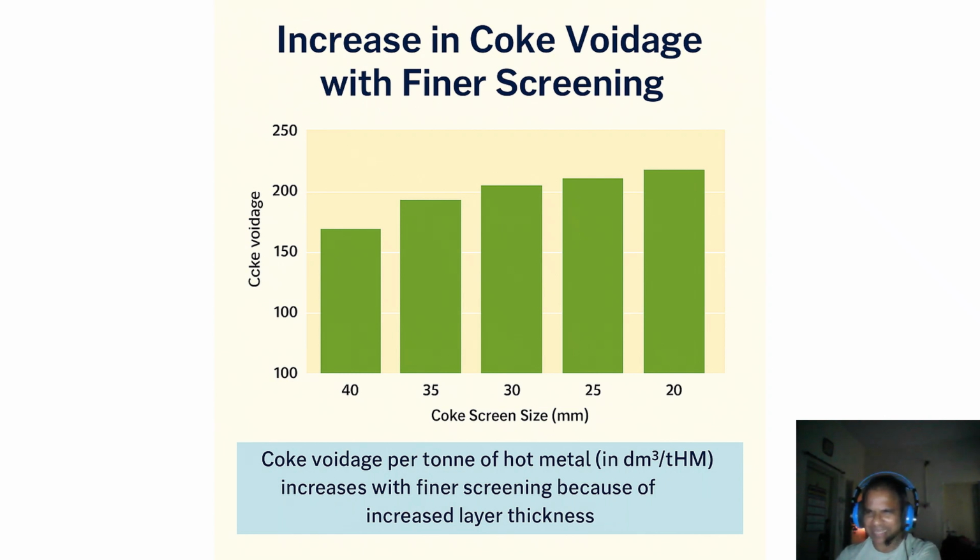So we can say that a larger aperture thins out the coarse coke, improving the gas permeability. Yet in this situation, they generate more nut coke, which must be blended wisely into the ferrous layer, and we must not ignore this balance.